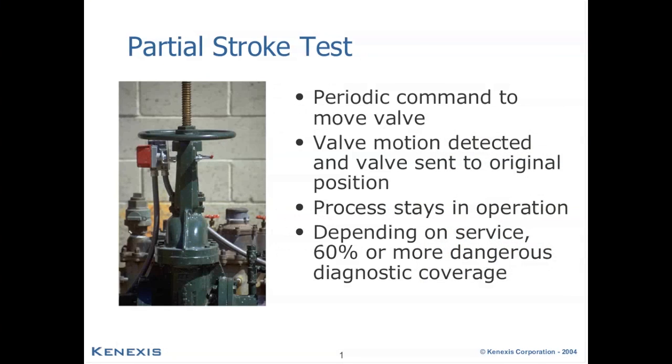Partial stroke testing is a type of diagnostic function, and we measure the ability of a diagnostic function to detect failures by something called its diagnostic coverage factor.